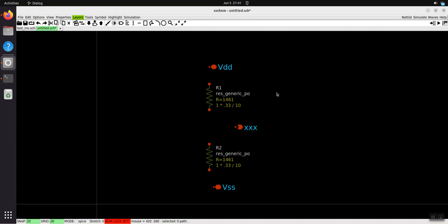The wiring tool is a little bit different than other wiring tools, in that you hover over what you want to start, press the letter W, and then it'll draw, and then connect it to where you want to go, and left click it. Like other tools, you might keep using the wiring tool, but you still have to hover, press W, end it with a left click. Start, and then I want to double click here and move it so that it looks good.